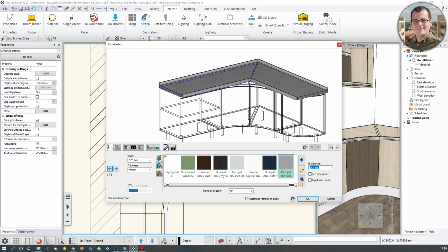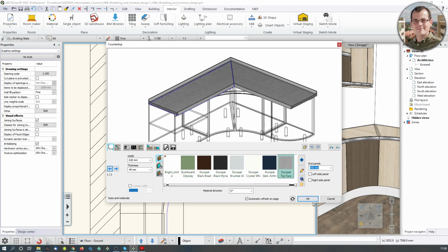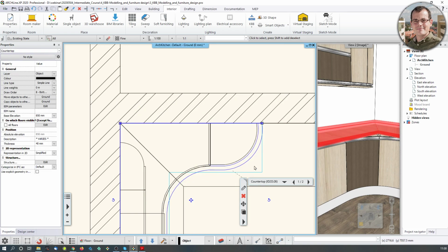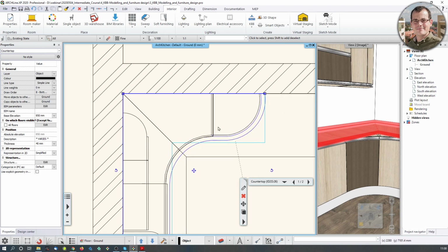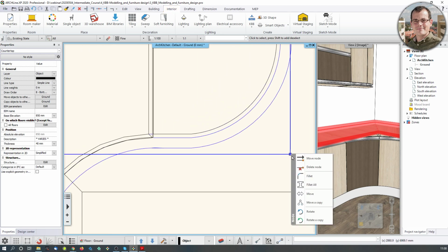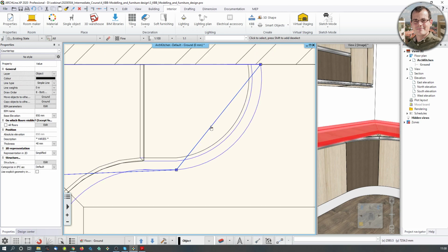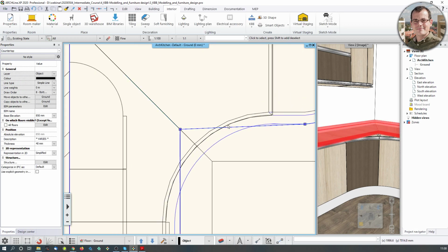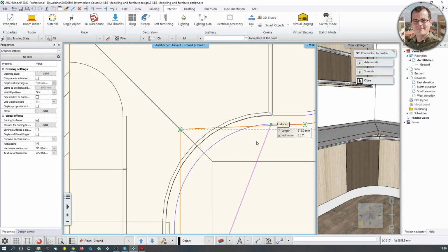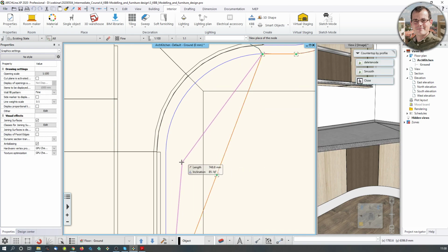And how do we do that? Well, first thing we have to customize is the layout itself, or how it looks like, how the bands are going. But the problem is that if I click on the worktop, I can't access these nodes. Well, that is because for that you need to enter what we call a component mode. In the component mode, let me just hit escape, just hit Alt, and then click on the sides, you now have access to all the nodes it has to offer. So let's just hit the nodes and move it to someplace else. I think it should go here, and this part has to be curved. And let's proceed. This node comes over here, and there should be another node, so I'm clicking insert node here.